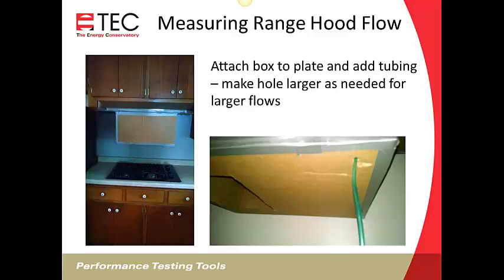If you've got larger flows, if you've got a cardboard box, you can make that hole bigger, or you can make that hole smaller by taping it using some duct mask or tape or cardboard and tape to make that hole smaller. Because remember, the first step in taking the flow using this device is to make sure that the pressure in the box is between 1 and 8 pascals.